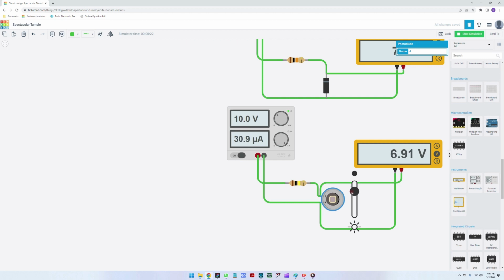And when we start this, you can see that when it's full light outside, it's 0 volts, and as the light is diminished, you can see and you can measure these values. This is very important because you can measure, okay, now it's getting a bit dark. Now, for example, you can turn on the sprinkler system or anything like that. Okay, so this is a photodiode. You can play with it, get different output voltage levels here, depending on the external light.